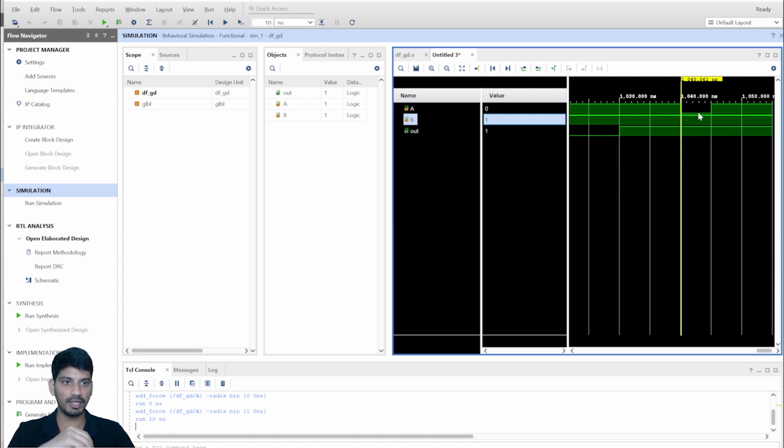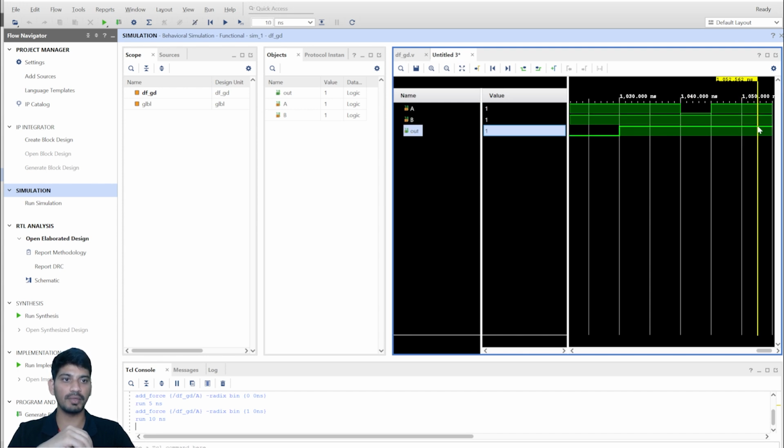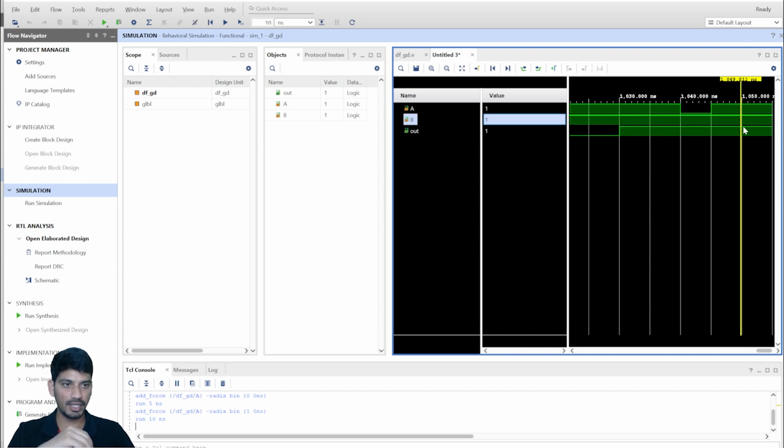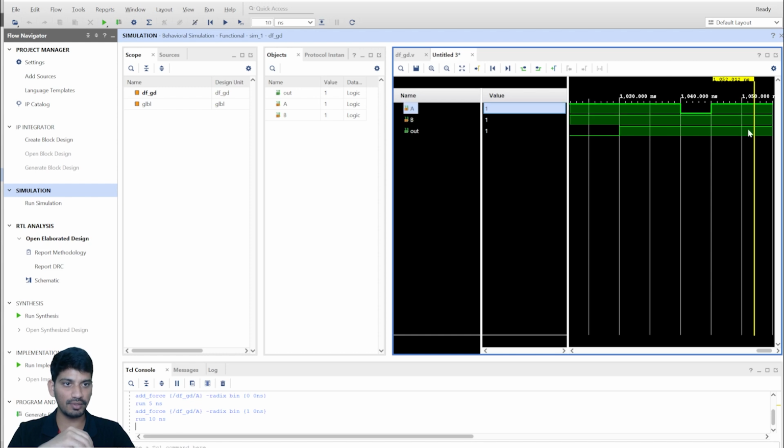Then we expected this 1 into 0 should appear here, but still it did not appear here, because after 10 nanoseconds has passed, it will evaluate the expression A and B at these inputs, not these inputs, because these inputs are already forgotten by your circuit because it went into the delay, and then it will evaluate the expression at this particular time period, right?